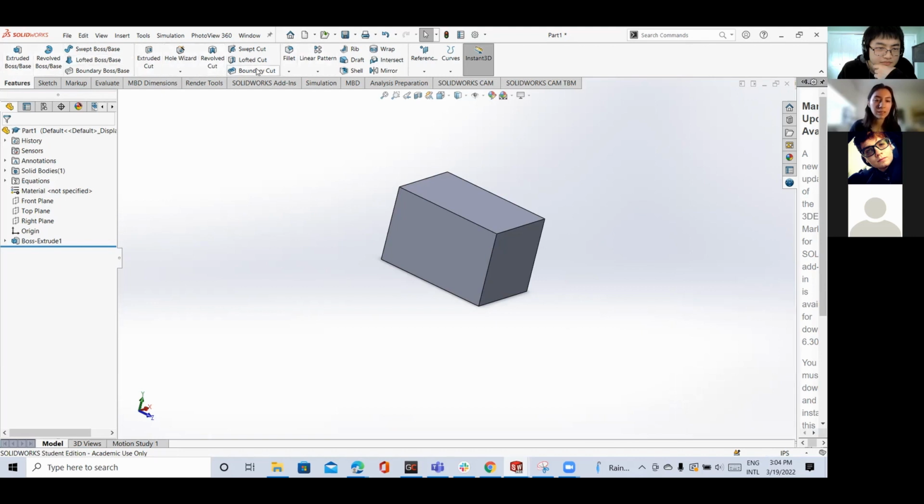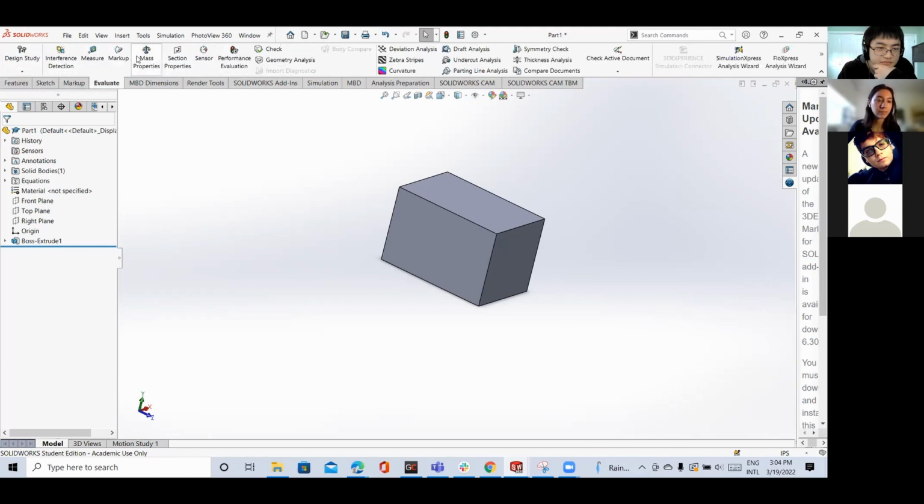So now I need to go to evaluate, and we're just going to make sure that this worked. So measure, and this is now 4.5, and this is 3. That is, hold on. I think when you entered in the global variable for it, it evaluated it or something. Because when you enter in A or banana or cat or dog, when you hit enter, it changed to the number it represented on the smart dimension or on the extrusion. Something's not right here.